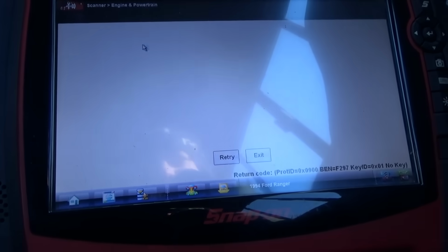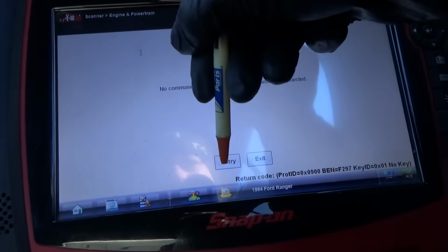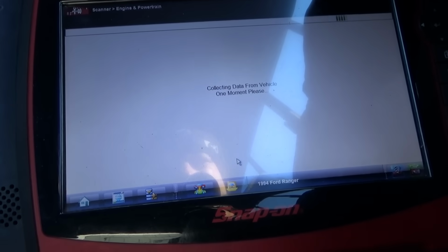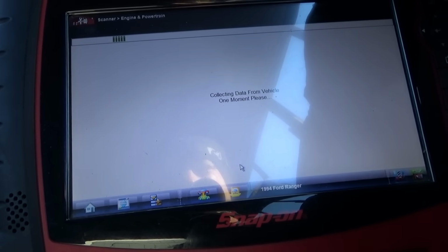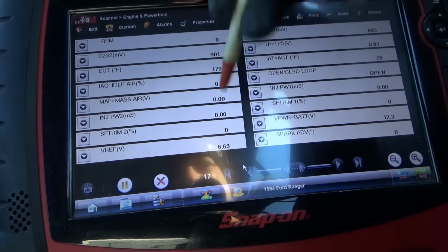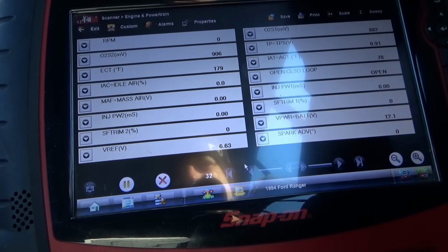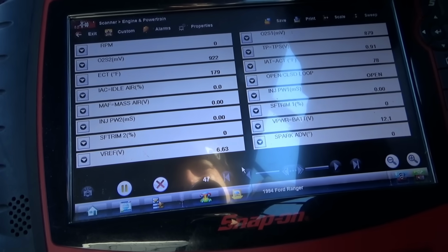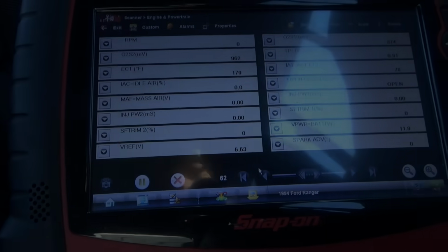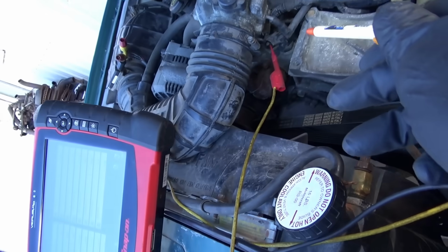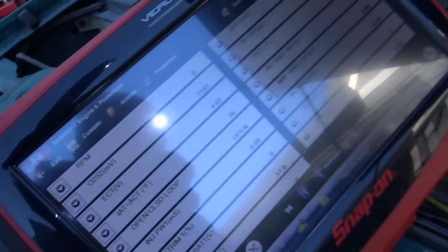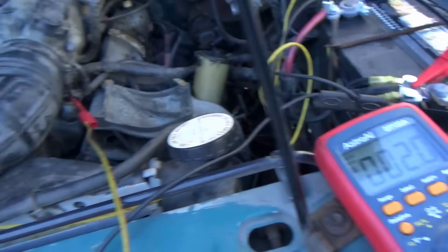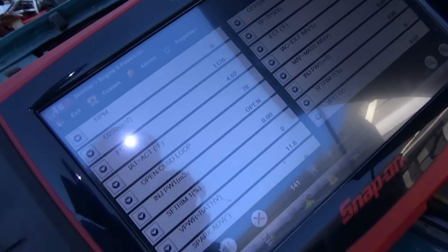Let's see, shut it off. Key back on. 6.63. So weird. So I got the engine coolant temp sensor unplugged. 4.7 volts. We're reading 4.6 on the scanner. That's close enough. If I pull this down with my test light to 0, we go to 0. That's perfect.